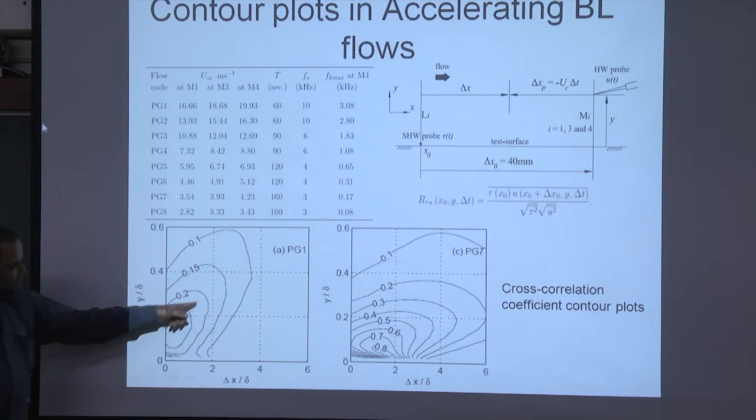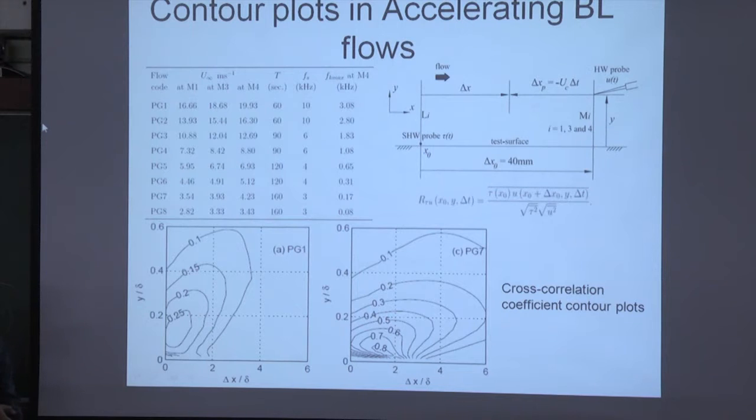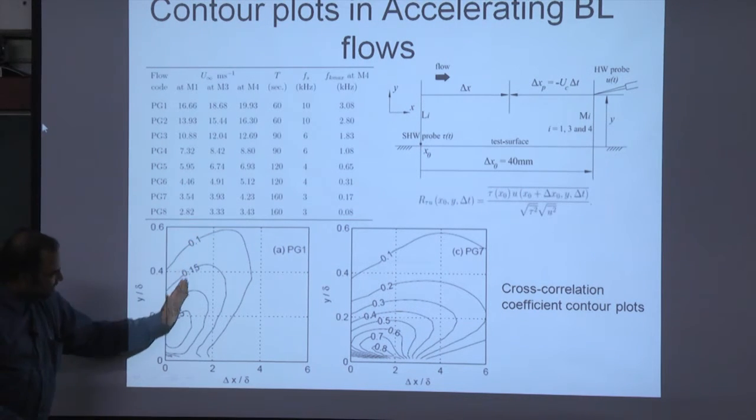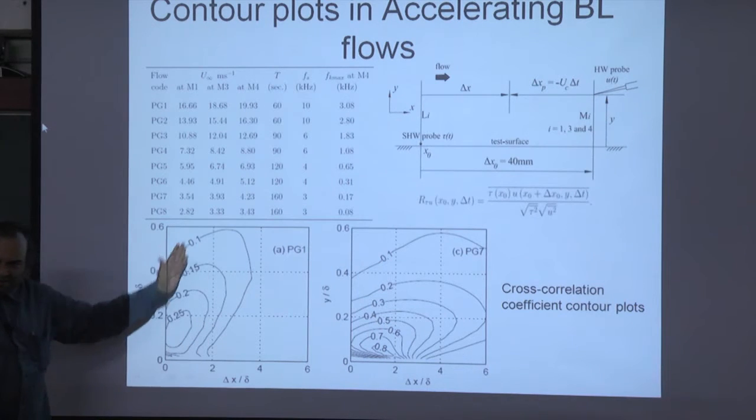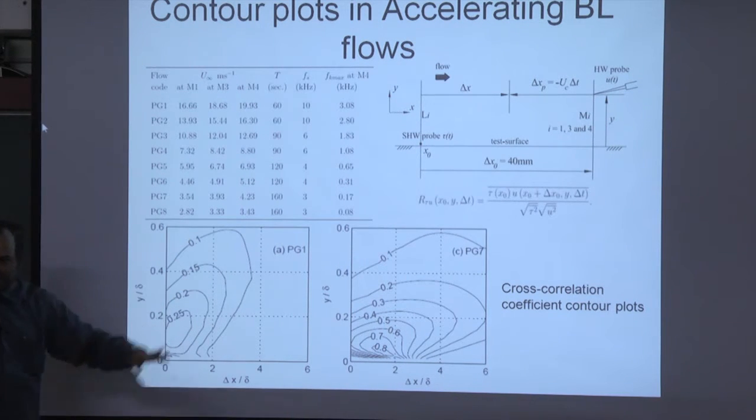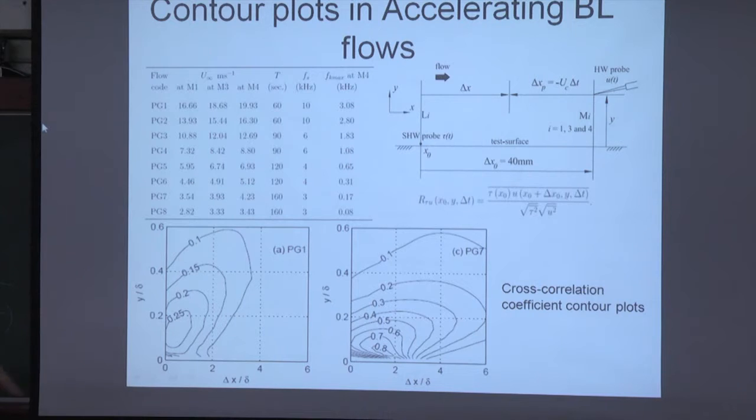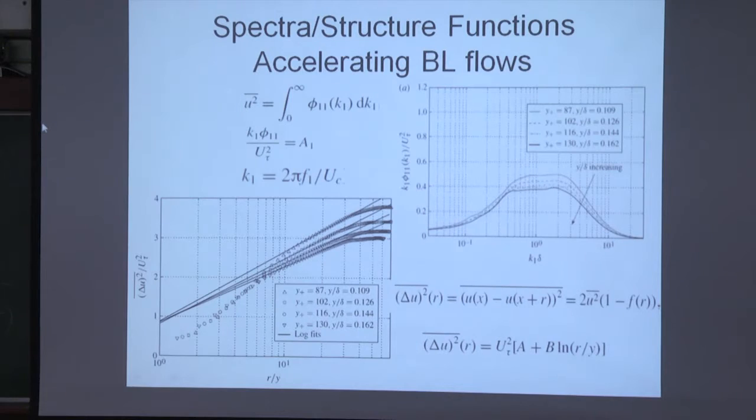So if you connect all these, the procedure I have not explained here, you get contours like this. It will give you structures which are leaning like this, you see. So it is an indication of the sort of eddying activity, large eddies especially. Remember, these correlations are primarily a signature of relatively large eddies. Okay, and I can do this sort of cross correlation plots.